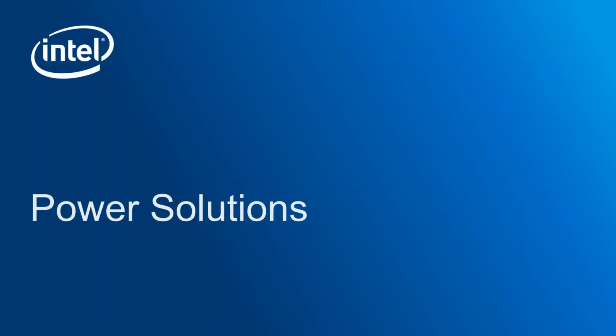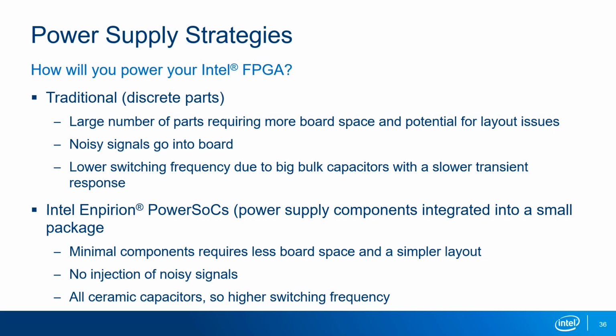So let's take a look at different power supply solutions. Traditionally, devices on a PCB are powered by supplies built from discrete components. Supplies like this typically require a large number of parts that take up valuable real estate on your board. On top of that, more parts means more layout requirements that, if not followed, can lead to problems. Using separate components also means that noisy signals between parts can go into the board, causing issues in other parts of the design if it's not properly isolated.